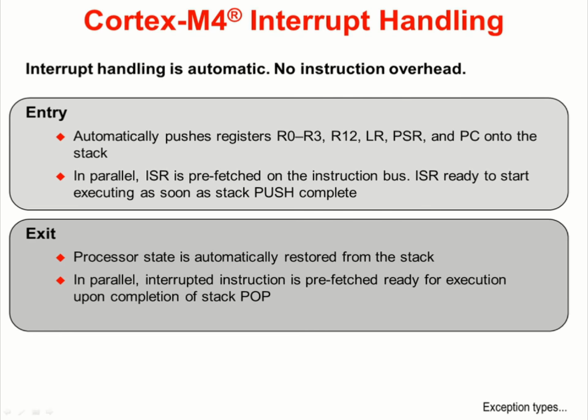On the exit side, the processor state is automatically restored from the stack. In parallel, the address of the interrupted instruction is prefetched, ready for execution upon completion of the final stack pop.